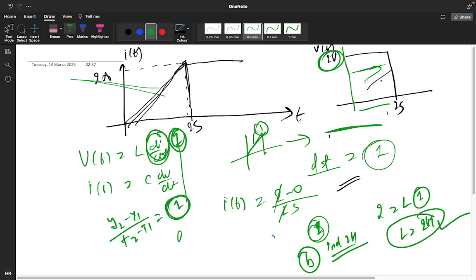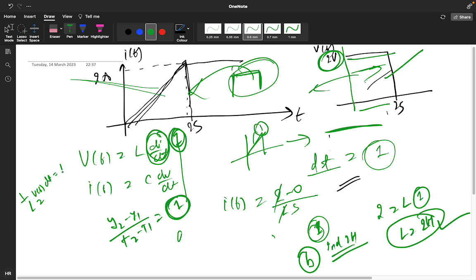Okay, and the integration of this, you will get the triangle. If you differentiate the triangle, you will get the square pulse. If you integrate the square pulse, you will get the triangle. So with the help of this also we can find the value of an inductor, by integrating, taking the value 1 upon L, v of t into dt, to get I. This is in the form of integration. By this also you will get the value. Okay, so this was the story of question number 21.